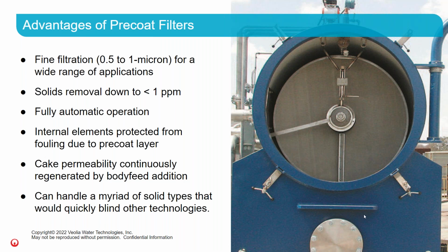Another advantage we have is because the leaves have a Precoat layer on them, the internal elements are protected from fouling, and this can keep the integrity of the leaves. And also, there's an ability to add body feed to your application.